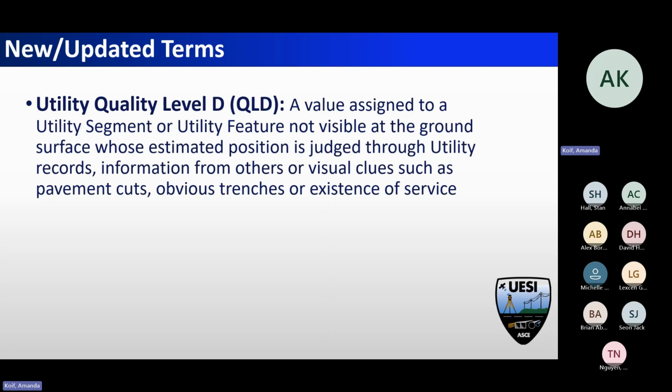And there is something there that we need to maybe investigate more, and that can go in the utility report that says, yes, I need to do some further investigation, whether it's exploratory, vacuum excavation, or something else. That could be part of the utility report that, hey, I know there's something there, but I just don't know where it is. And if it's important to the project, then we need to look at it some more.